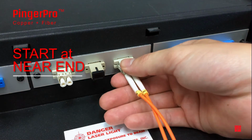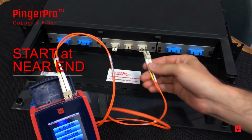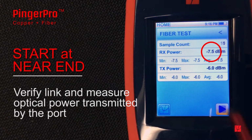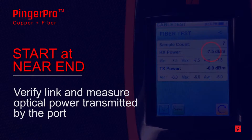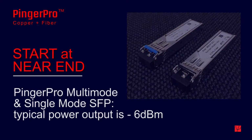Start by disconnecting the fiber cable at the connection port at one end of the link. Use the fiber patch cord and connect the PingerPro to the device port. Verify that a link is established and measure the optical power transmitted by the port. The measured level should be compared with the manufacturer's specification for the SFP or GBIC module. The PingerPro multi-mode and single-mode SFPs have a typical power output of -6 dBm.